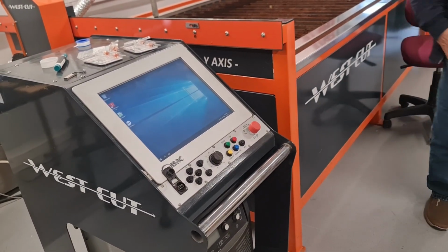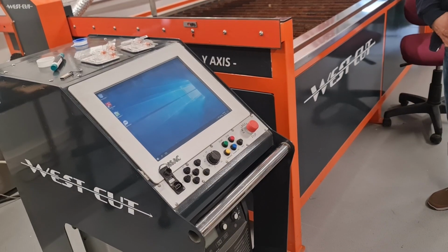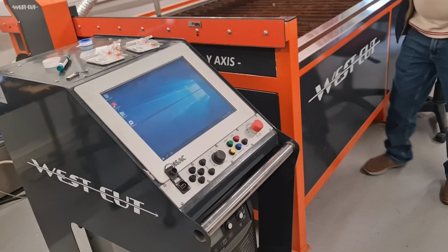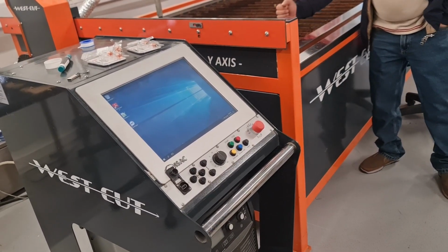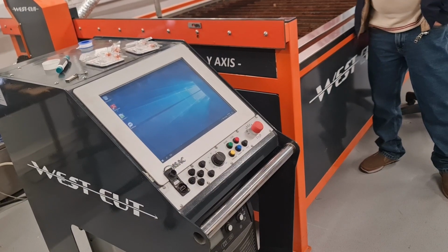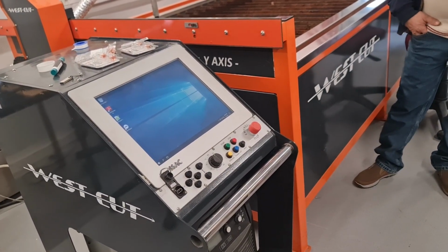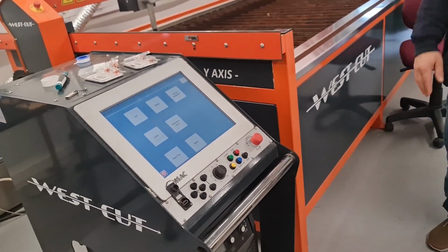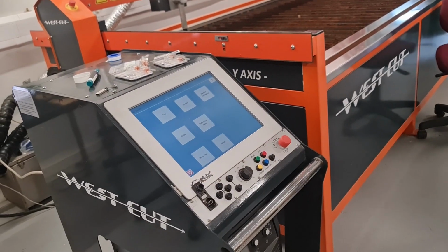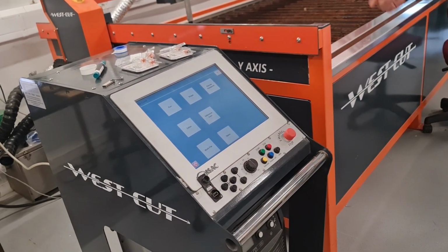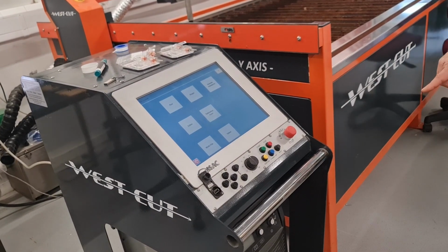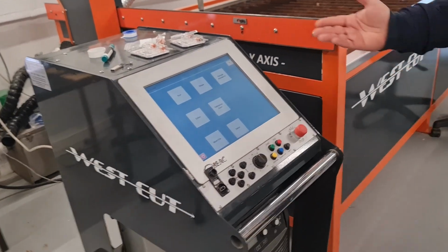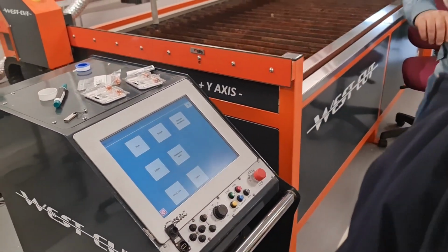How is it finding that? Is it conductance? Now there is a floating torch. The torch is floating, so when it goes and touches the material, it will find the switch and it will find the height. Z is an independent axis. Then there is another operation, which is with the voltage control. So it will read the voltage from there, and it will try to correct the gap. So eventually, the machine will start like that always.